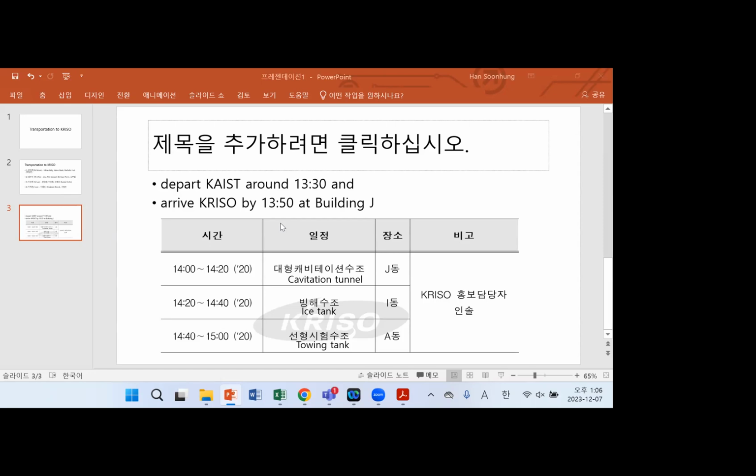You can think this is coming back. So when it's loaded onto the ship, the displacement should be, the draft line should be moved down and increase the displacement to compensate for the force coming from the cargo. So still there is another balance, right? And then you see that the freeboard is not so large now, right? So if I load more weights on it, there can be a deeper draft line. So the freeboard is decreasing, so you can say this is not a safe situation.